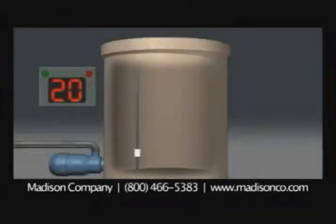Madison Company continuous level float switches are designed for vertical mounting in a tank. DC power is applied to the switch, which can then provide a 4 to 20 milliamps, 1 to 5 VDC, or a resistive output signal that can then be routed to programmable controllers, microprocessors, or other readout devices.